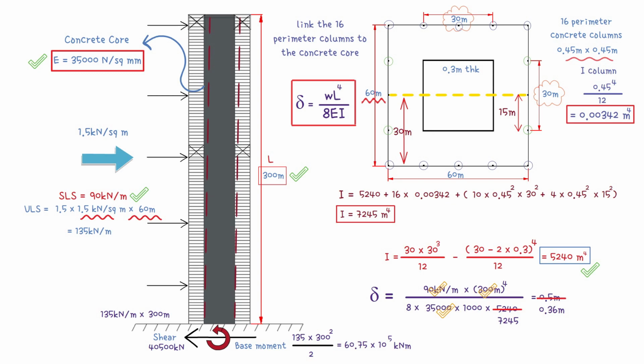It should be noted that this approach will underestimate deflections, because it does not account for the stretching and squashing of the members due to tension and compression. Although, the result is good enough for checking the output from a computer-based solution, or for providing a guide to a likely response during the early phase of a design process. We always recommend you compare the results from your analysis software with your handwritten calcs.